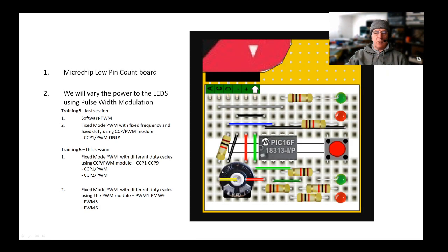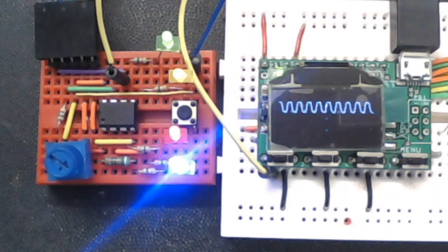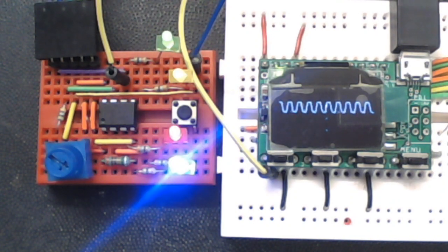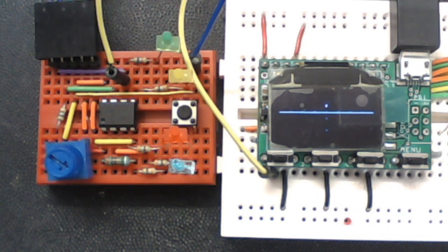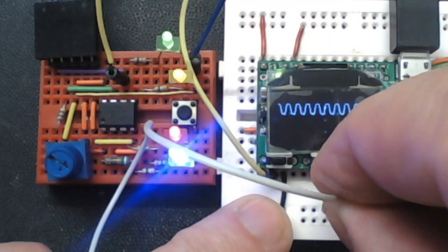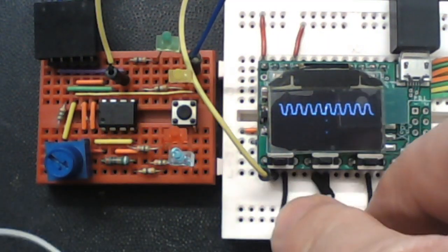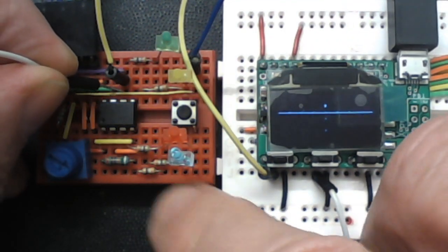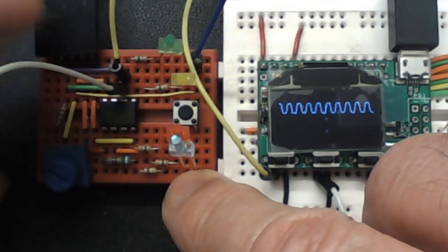we have an oscilloscope. Okay, so let's look at that oscilloscope now. Here it is. This is the oscilloscope. It's hooked up to one of the LEDs, and you can see there are 4 LEDs flashing, but that's where we left it after the previous training session. So I'm going to quickly hook up another channel of the scope for this session. This is a dual channel scope, so I can quickly insert another little wire into here, and if I push it into just below the previous one, I can then pick up the second channel.